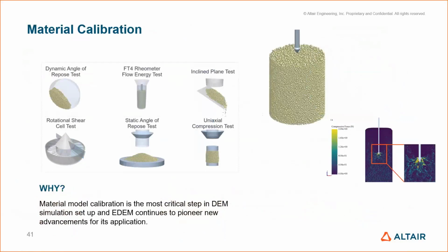So within EDEM, we want to calibrate simulation results against known experimental data. The topic of calibration is a webinar in itself, but just really to highlight, there's a series of calibration kits in EDEM. These are a collection of standardized tests and associated analysis scripts which allow you to automate a lot of the calibration workflow. The calibration kit removes the need to model the standardized tests, which reduces the amount of engineering time required to calibrate a material model. It just allows you to use the software for design purposes.